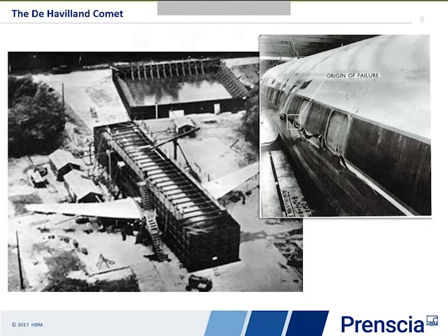They built it up in this water pressure jacket, and they changed the internal water pressure in order to represent the ground-air-ground pressure cycles. After just 1,800 simulated pressure cycles, meaning a total of 3,000 ground-air-ground cycles, the fuselage failed, as you can see in that right-hand picture.